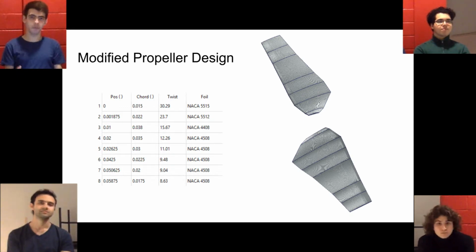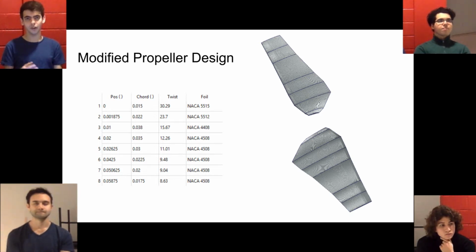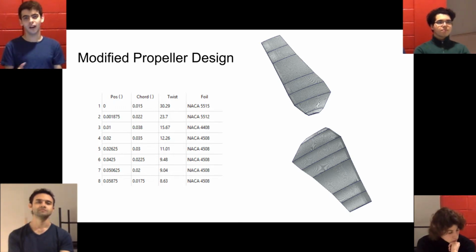We also dropped the condition of keeping efficiency constant around the whole blade because the root had a way lower efficiency than the rest, and efficiency was instead kept constant for the 5 sections closer to the end, and this gave us better results.